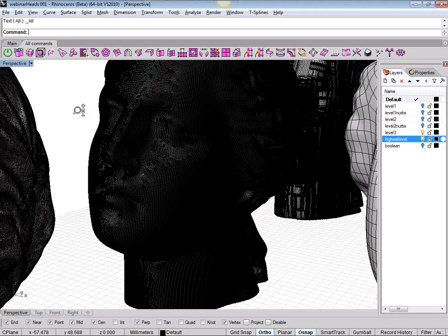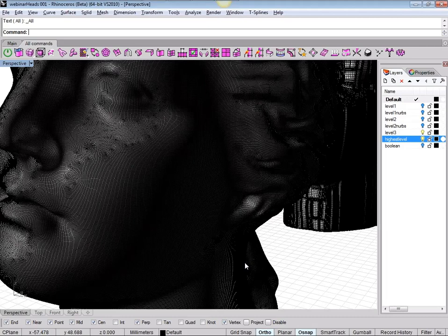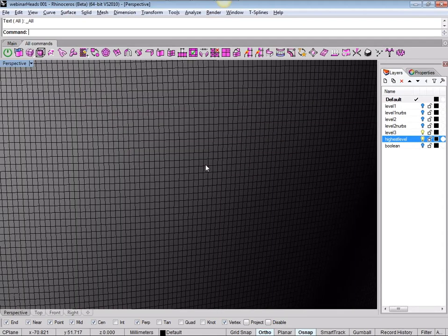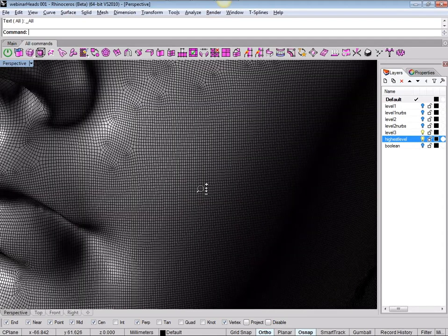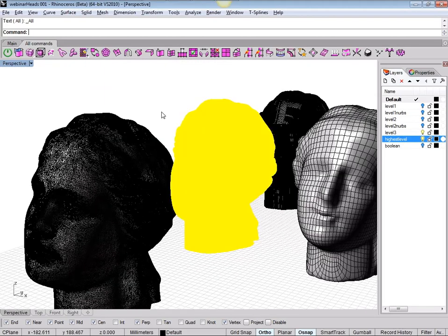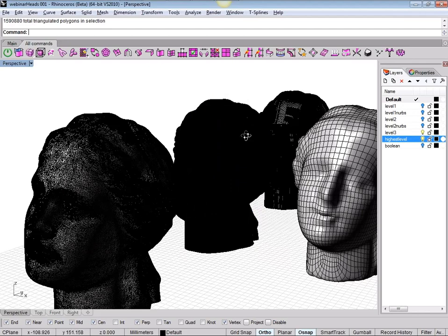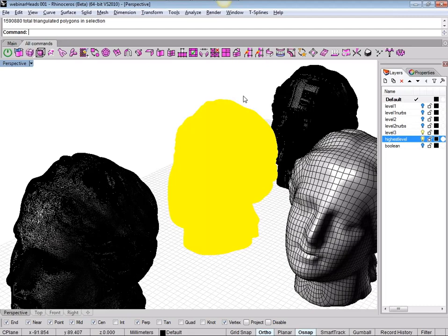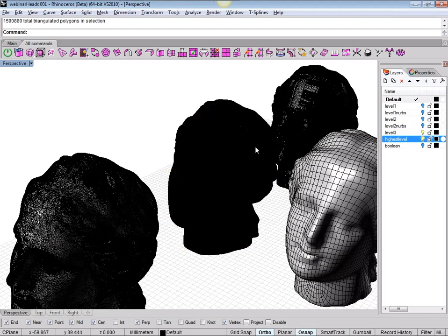Here we've got our ZBrush conversion. This is all quads, but there's a lot of them. If I convert here, it's going to take about 15 minutes. Let's see, poly count. This is 1.6 million polygons. Now this converted in T-Splines. T-Splines converted this, but given the hardware that I have, I'm going to have lags sculpting with it.